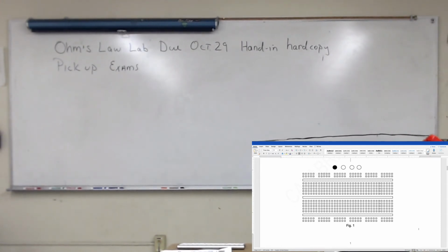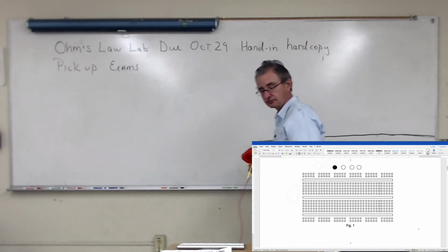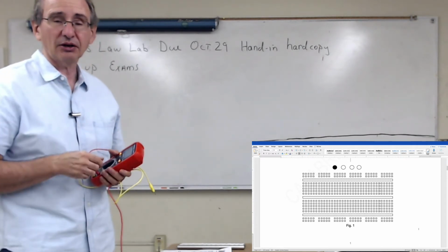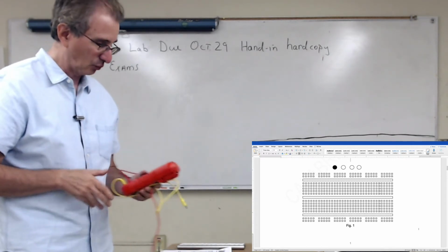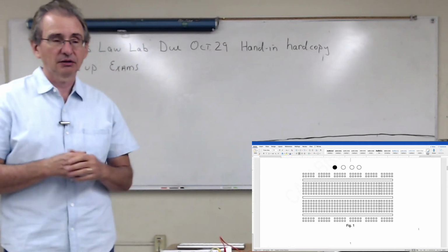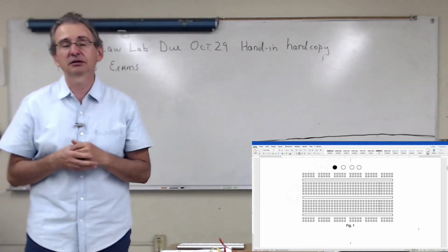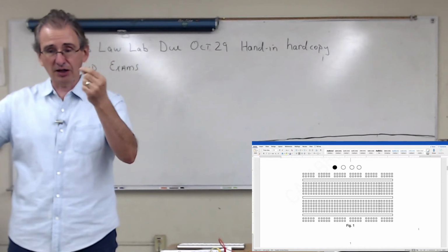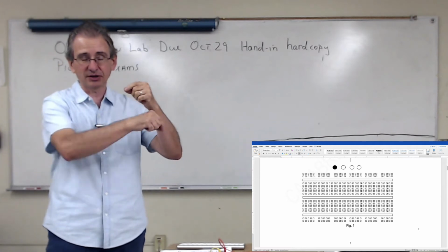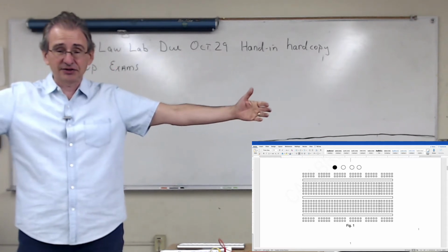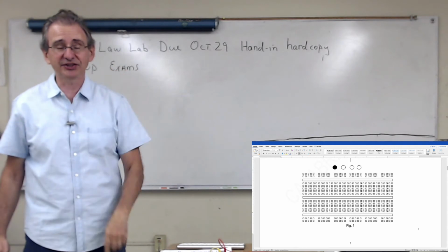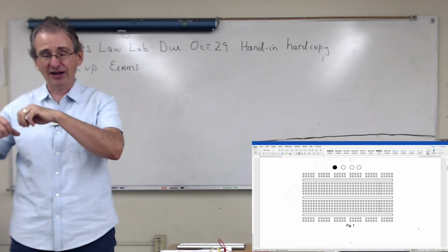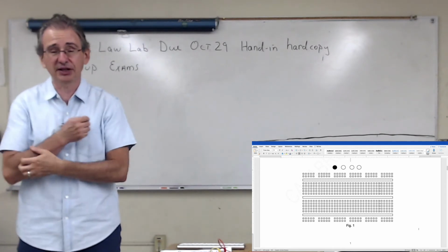In the old days, the Christmas tree lights were all connected in series. So if one of the bulbs went out, everything went out. And what one would have to do if they didn't have a multimeter was take another bulb that they knew worked, hopefully it worked, and go one by one and replace the bulbs in the set of lights with the one that works and see which one is dead. Okay, so if you replace a bulb with your working one and all the lights go on, that means you know that bulb is dead.